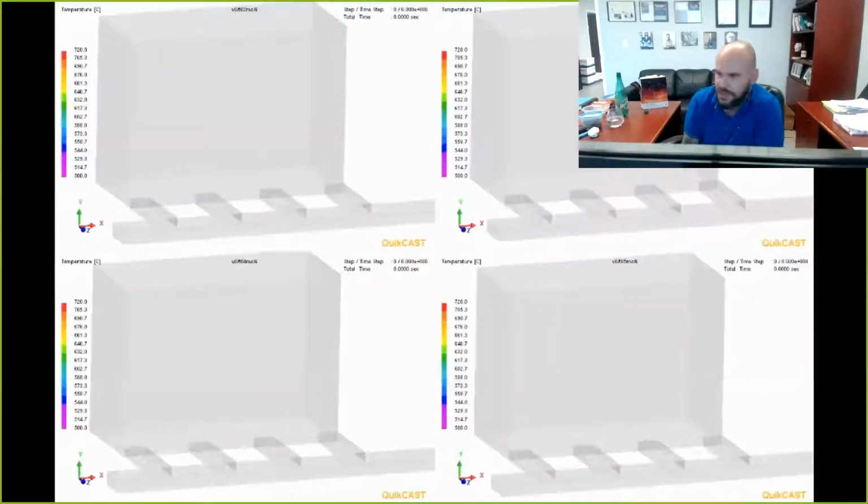All right. This brings us to a simple thing. We can't slow down the metal by expanding the cross-sectional area because that results in the entrainment of oxide films, surface films, air bubbles, sand from the mold, decomposition of the mold. Everything starts falling apart, and we've gone to hell, right? The problem is now we've got to deal with the velocity issue. We know how to deal with turbulence if we design by geometric constraint and only allow a perfectly designed pathway for the metal so that we're hugging it into place. We understand that's the case.